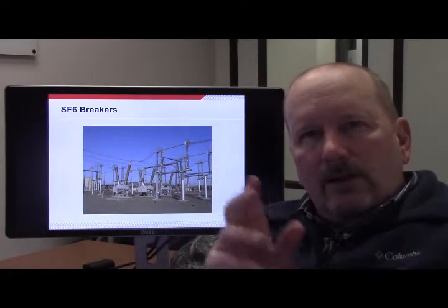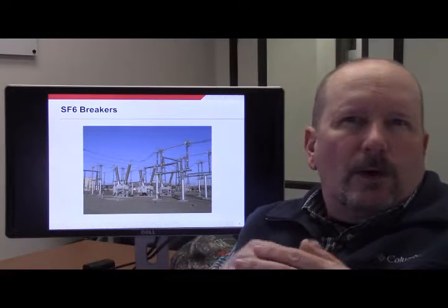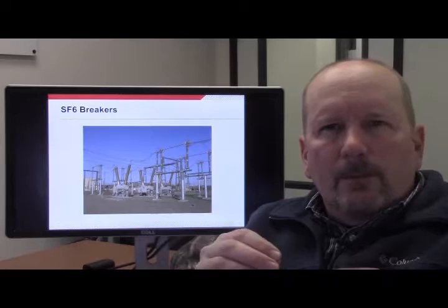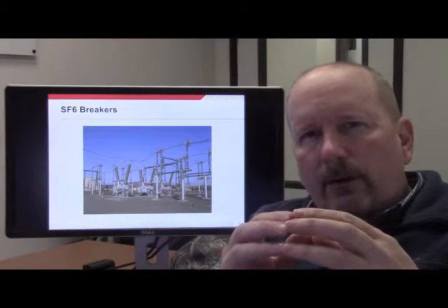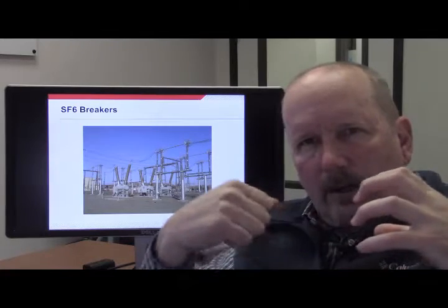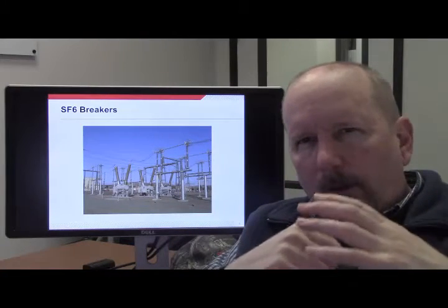And by ideal, you might think, well, you'd want a perfect insulating medium like vacuum. Well, there's a problem with it. Vacuum is such a good interrupter that as contacts are pulling apart, it actually chops the current.